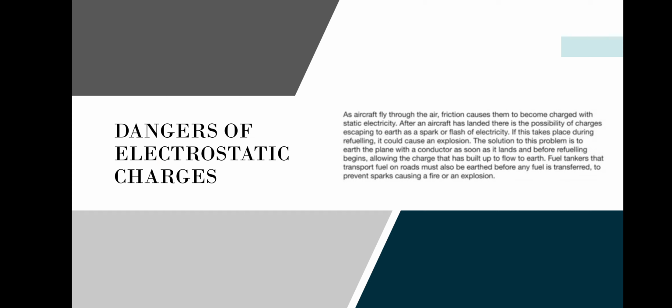Lastly, we have the dangers of electrostatic charges. As aircraft fly through the air, friction causes them to become charged with static electricity. Now, static electricity is very dangerous. After an aircraft has landed, there is a possibility of charges escaping to Earth as a spark or flash of electricity. If this takes place during refueling, it can also cause an explosion.